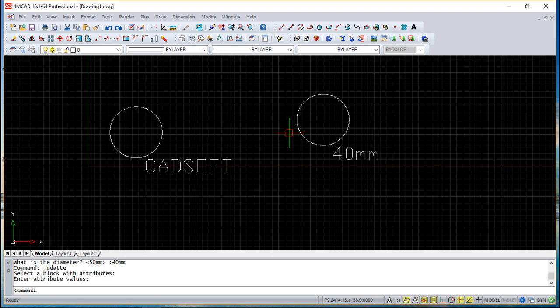You have three different types of export files, but the idea is to build a kind of database or whatever if you have multiple attributes inside your drawing. So how can you do this? You can invoke this command, so dda and then this one, so dda t text.